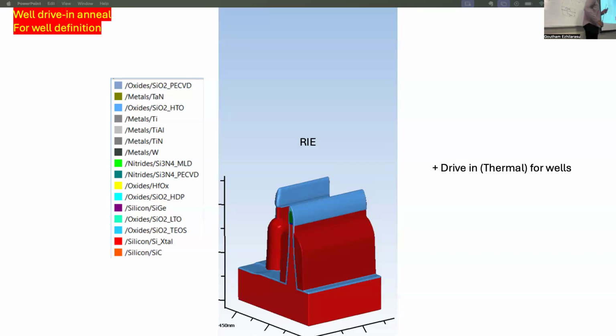But if you're doing ion implantation, remember ion implantation is directional, right? You're going to shoot it in one direction. So when you have this fin-like structure, if you're doing ion implant from the top, it'll end up heavily doping this region, but lightly doping this region, right? Usually you don't care much about this region. You only care about the doping of the sides. So typically what people do is they dope it at an angle. They implant once at this angle and then once at the other angle, right?